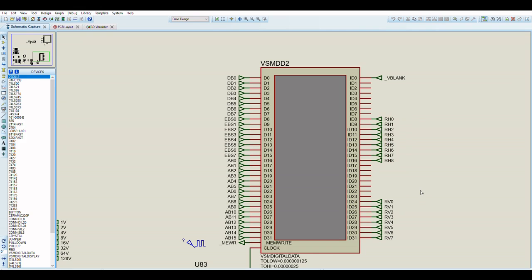However, the rendered screen is 256 pixels by roughly 256 pixels. However, there is horizontal overscanning for the borders and the flyback period, etc. And then we've got the vertical pixel, or raster line, if you like, which is 8 bits wide. These on the right here are inputs, because the digital data generator waits for expected triggers from these values on the input, and then it will output one or more bytes based on some textual definition and also some binary data files and stuff like that.